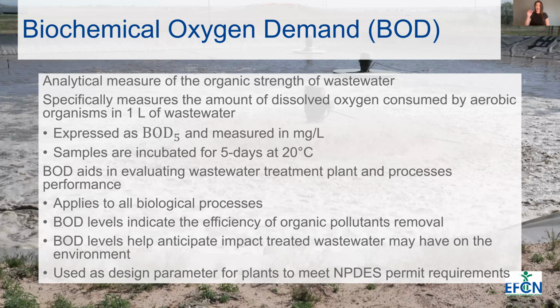This typically refers to a test expressed as BOD5, measured in milligrams per liter, for samples that are incubated for 5 days at 20 degrees Celsius. The BOD is measured before and after to calculate it.